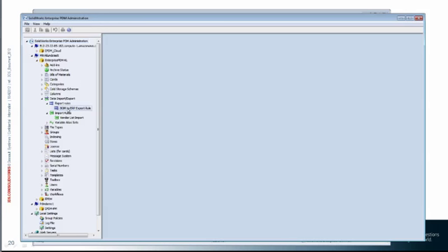We can have these rules that I alluded to earlier in the presentation, where at certain points in a workflow you might want to automatically send out an XML file that can be read into your ERP system. You can do that with this function. And we can have alias sets. So if you've called the variable, let's say, part number in your Enterprise PDM, but it's part underscore num in ERP, you can use that alias set so when it goes out, the variables are identified correctly. Okay, and that is kicked off in our workflow.